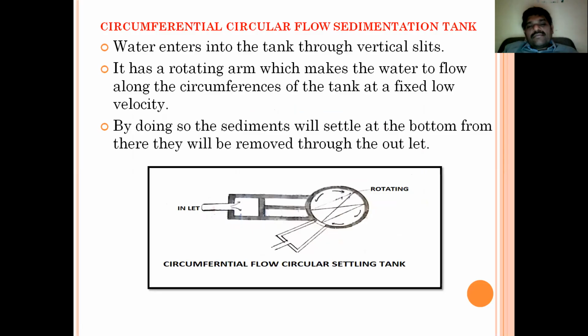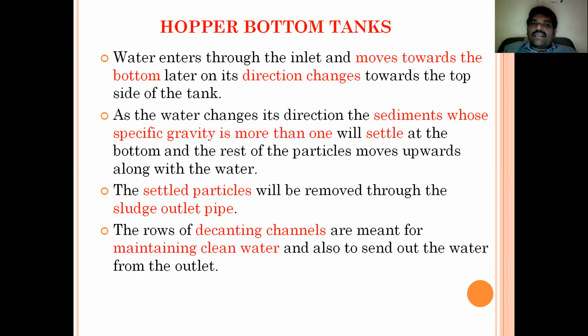Make sure, whenever you encounter this question, you write detailed notes on sedimentation tanks: rectangular tanks, circular tanks, and the next one, hopper bottom tanks. Hopper, see, you're collecting at the bottom. Hopper bottom means a funnel shape, where the settling particles are taken off from the bottom.